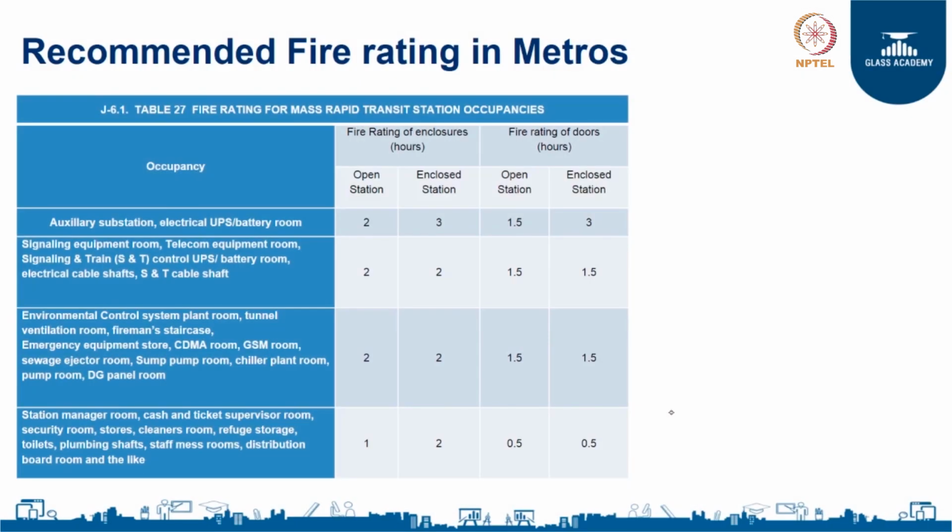These are some of the recommended fire ratings in metros as per the National Building Code. So, again you can see a lot of machine rooms and control rooms, and you see that the fire rating requirements are between 1 hour and 2 hours, sometimes 3 hours as well.